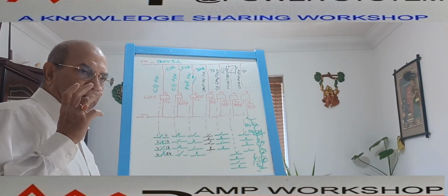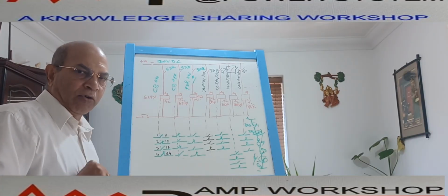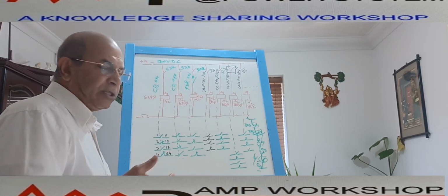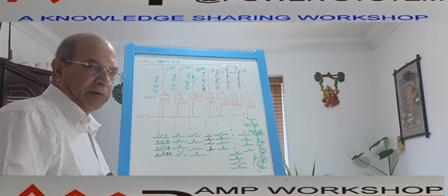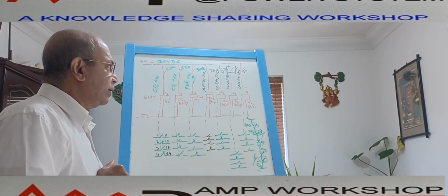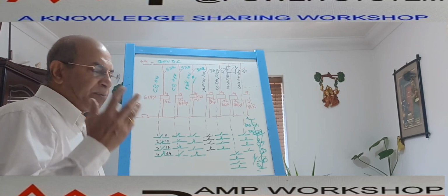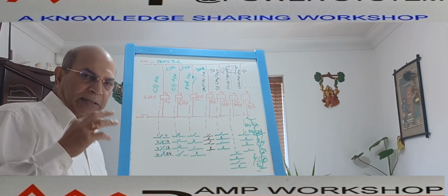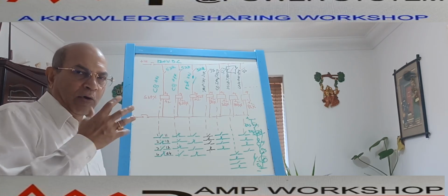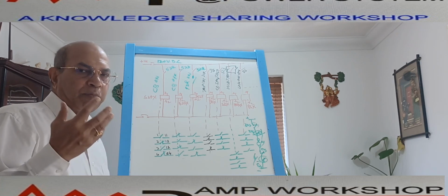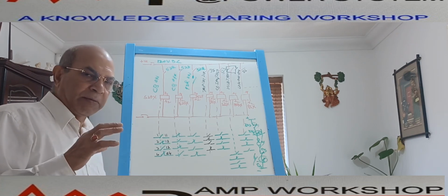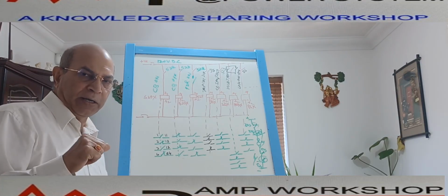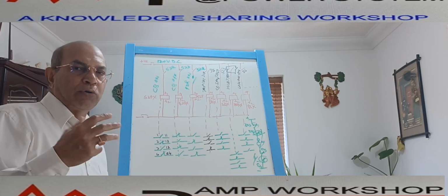So we have seen the breaker has auxiliary contacts. There are multiple auxiliary contacts, both NO and NC combination. Then the spring charge mechanism also has spring NO-NC contacts. Then the trip circuit supervision relay 95, which we have seen. The 95 relay has some auxiliary contacts, but the number of contacts on all these relays is a maximum of 4 or 6, or 2. Sometimes some of the relays have only 2 contacts. In some cases, maybe 2 NO, 1 NC; 2 NC, 1 NO; or 2 NO, 2 NC.